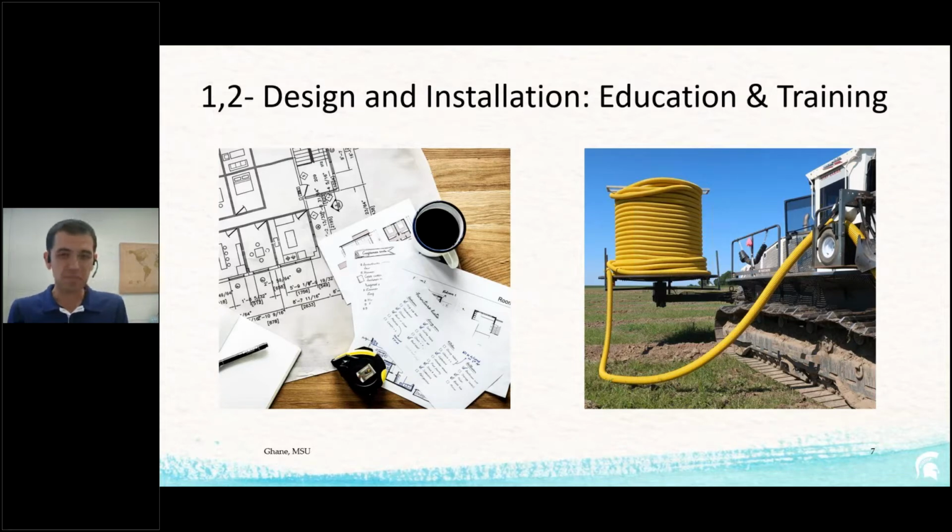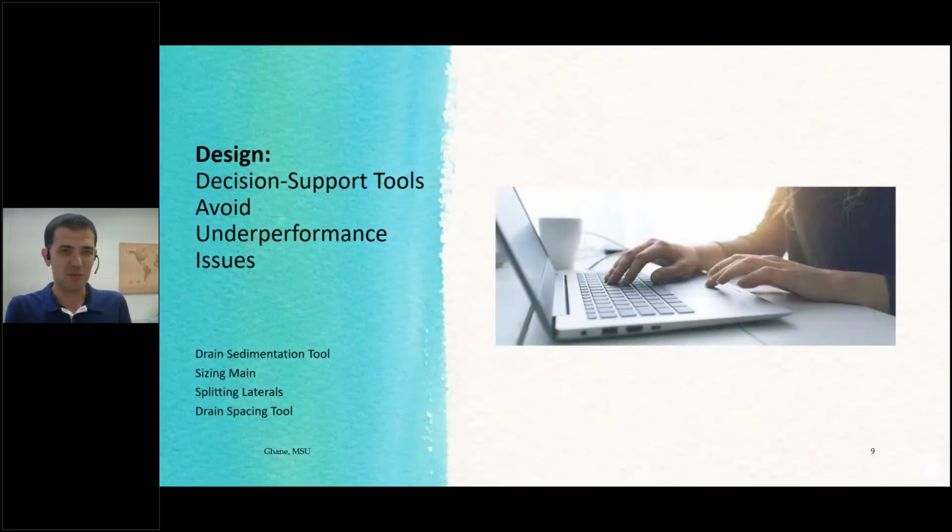But just briefly, keep in mind the ideal condition to install it is when the ground is the driest. You want to avoid those wet conditions because it's going to cause soil compaction. And also, if you do proper installation, you're going to be avoiding the root and sediment clogging problems, because that's one of those problems that also causes underperformance. I don't have time for those, but if you want to learn more about those, there's information on my website.